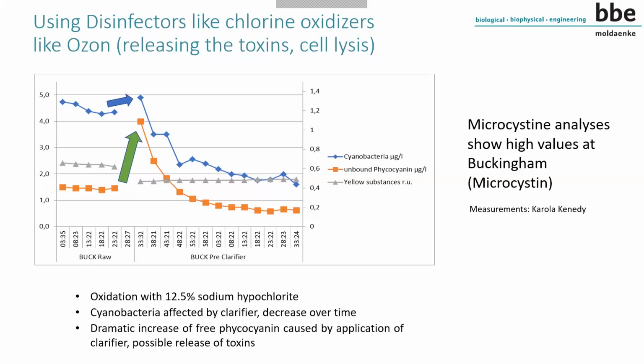And the last question, as far as I copied: what is the maximum depth we can measure with our handheld probes, for example in a dam reservoir? With the handheld probes, with the algae torch, you can measure 10 meters with a standard version. But there's also a special version that has a better plug for sealing. Then you can go down to 100 meters.